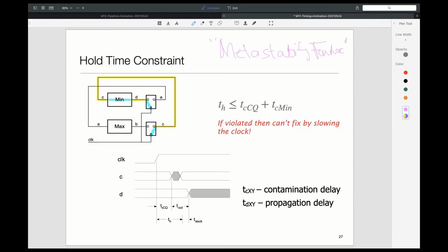So effectively it won't happen statistically. You'll have to be super unlucky for it to happen while your system is running. They design these things that way, and there are flip-flops called metastability hardened, which take extra effort. Your goal is not perfection, because you cannot achieve perfection, but to make sure that the mean time to failure is very large.